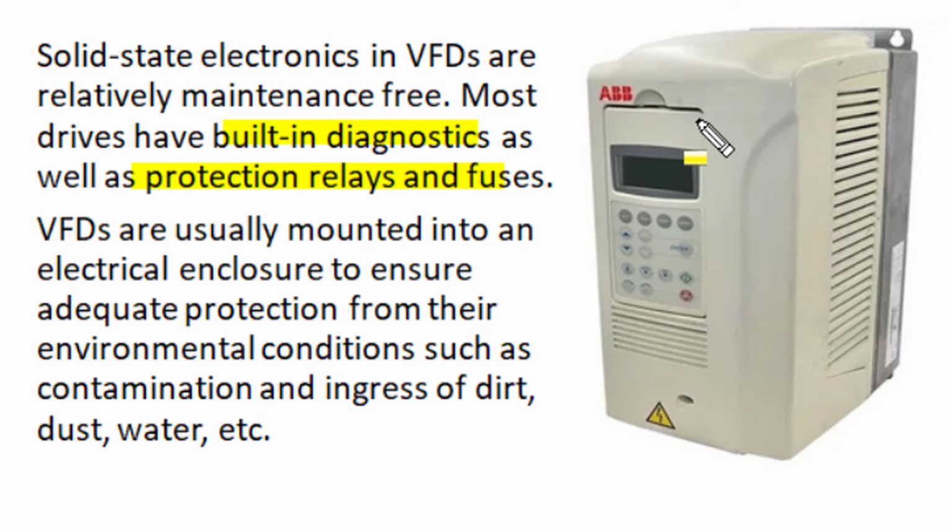The electronic components of VFDs are usually mounted in an electric enclosure that ensures adequate protection from all environmental conditions such as contamination or ingress of dirt, dust, and water, and there are ventilating and ducting provisions in the enclosure that provide required heat dissipation, ventilation and cooling to our power electronic devices.